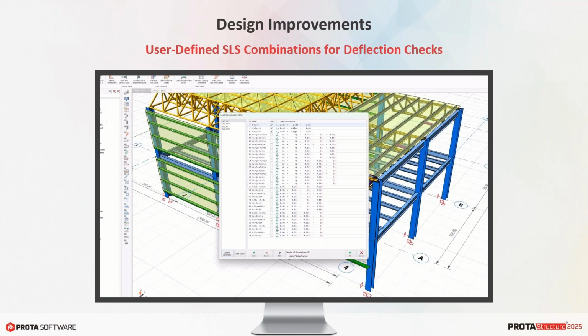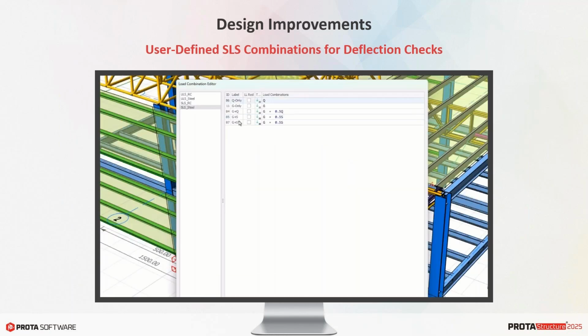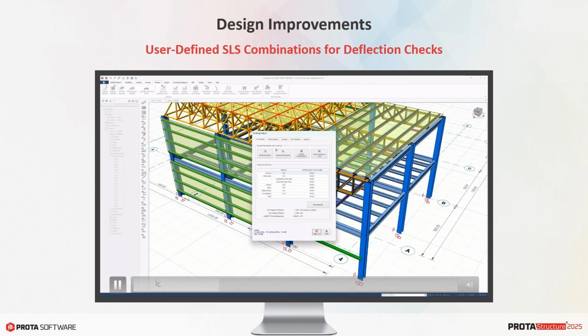So now you know that the new combination system in ProtaStructure is much more flexible. We now support separate ultimate limit state and serviceability limit state groups for steel and concrete members. A valuable addition to this ability is to create the user-defined serviceability limit state combinations.